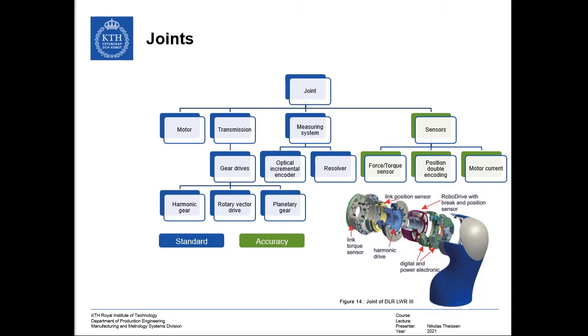The measuring system provides feedback about the motor or joint position to the robot controller on the driving side. This information is used to calculate the positions of the end effector as well as all links in space to ensure that no spatial velocity or acceleration constraints are violated.